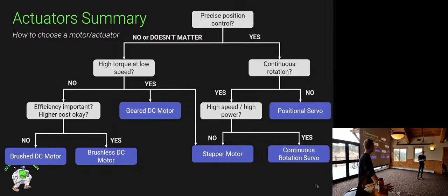One other thing to think about: yes, with a servo and a stepper motor you can do position control with both of them. Servos are generally a lot cheaper, but less repeatable. You don't see 3D printers using servo motors for position control generally. I've never seen one. But a stepper motor has precision at the micron level. It's repeatable, so if you tell it to go to the same location, it's going to do it every time. But it's not done through feedback internally. It's done just through the mechanism of how it's designed, and we'll talk about how it's actually controlled internally. But stepper motors are generally a lot more expensive and they can get hot too. You're constantly using a lot of power when they're just holding a position.